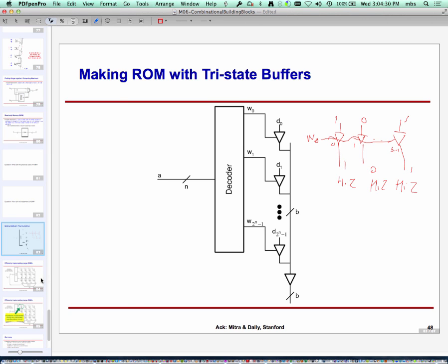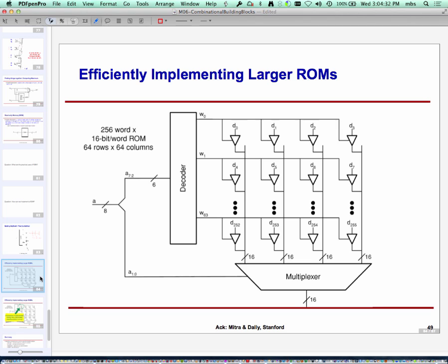What I'm going to do is divide my 32-bit address into two 16-bit addresses. One 16-bit address will tell me which row. The other 16-bit address will tell me which column. So now, what is 2 to the power 16? How big is that? 65,000 or so. So instead of 4 billion lines, I have 130,000 lines. Okay, big improvement.